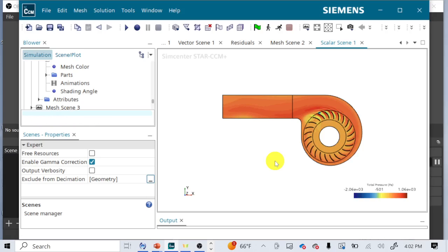Well, static pressure and dynamic pressure are related, right? How are they related? Flashback to middle of AE 160. If you change static pressure, what happens to dynamic pressure? If you change dynamic pressure, what happens to static pressure? Dynamic? Kinetic isn't a bad word for it necessarily, it's just not the usual one. But yeah, static pressure and dynamic pressure equal total pressure. If you change one, the other will change, assuming you don't add or remove energy. That's Bernoulli's principle right there. If you do not add or remove energy from the flow, total pressure will be constant.